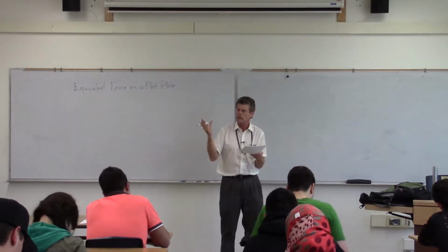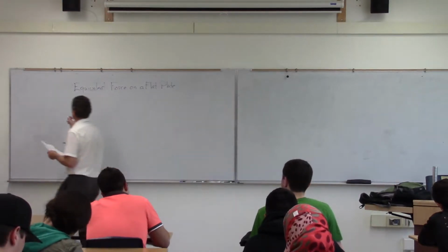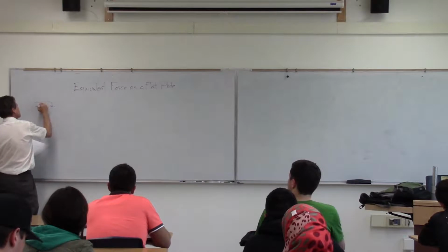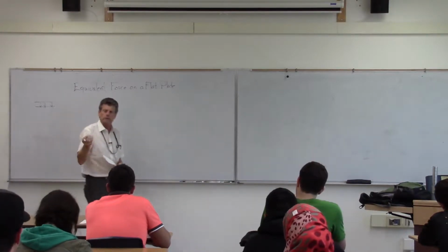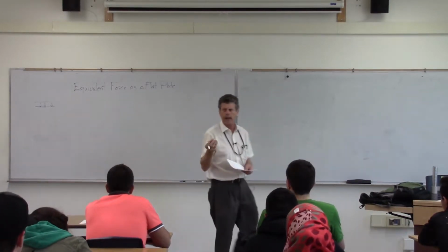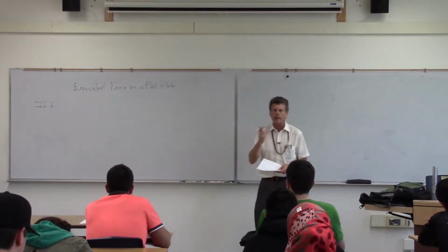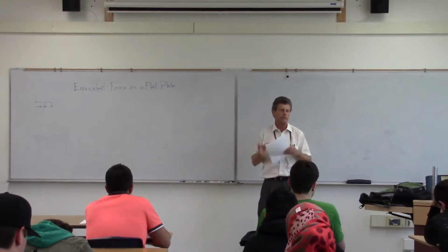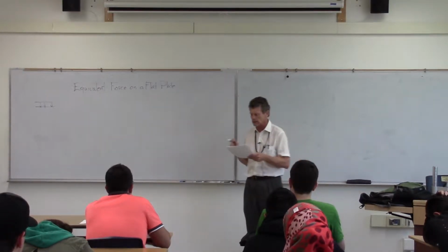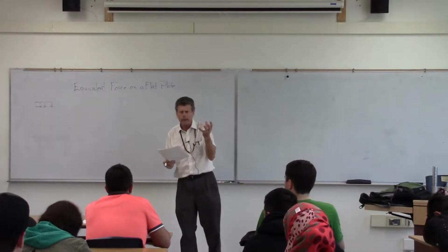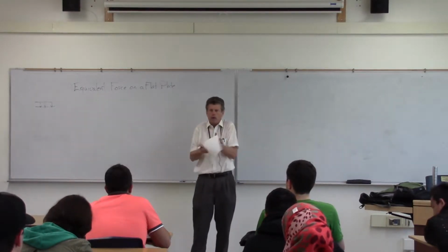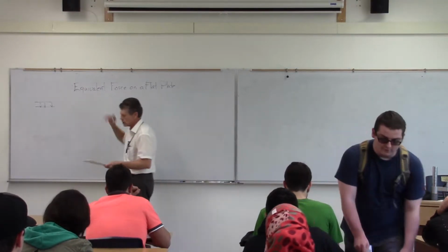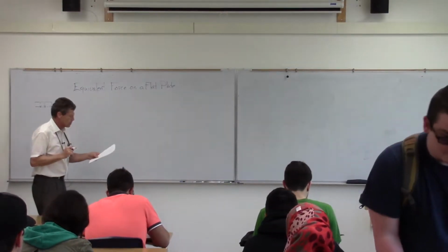Now remember, with our beam loads, we had a beam, and then we had some sort of a load that was expressed in terms of weight or force per length. So that's where we're going with that. And the way we get around that with the fluid forces is that we look at certain fixed widths. So we'll have this B characteristic that we'll be putting in there. And we put that B in there, and then all of a sudden we take out one of those dimensions, that Z dimension there, and we can deal with it now in terms of a beam force.